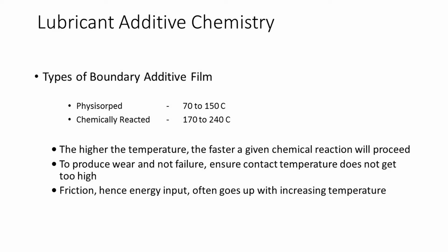These films may be partially destroyed and reformed each cycle. In other words, each specimen pass may knock the tops off a number of surface asperities, creating new active metal sites. The dwell time between passes allows time for the chemistry to work so that the film, chemical or physical, can reform before the next specimen pass. There is no way, of course, of telling how many asperities could be scraped off in this way, although it must be related to the wear.